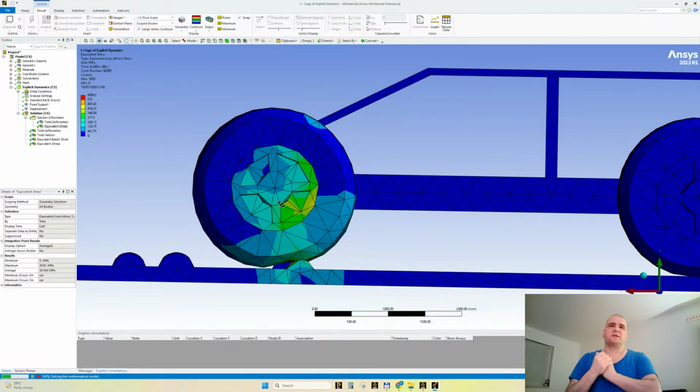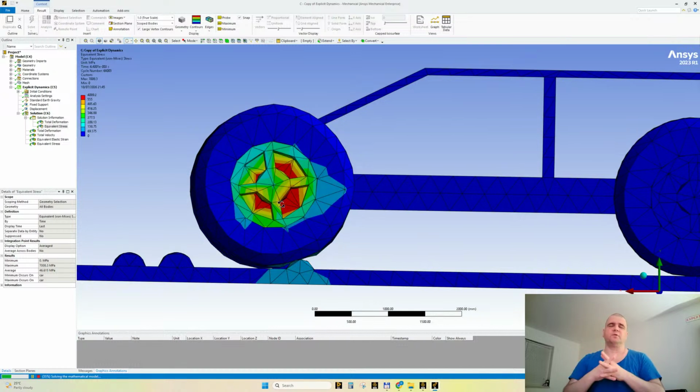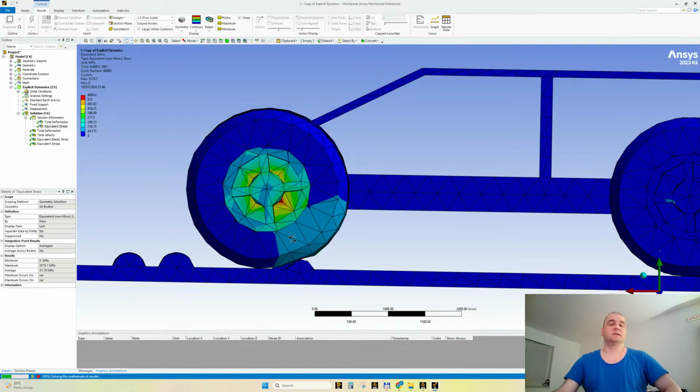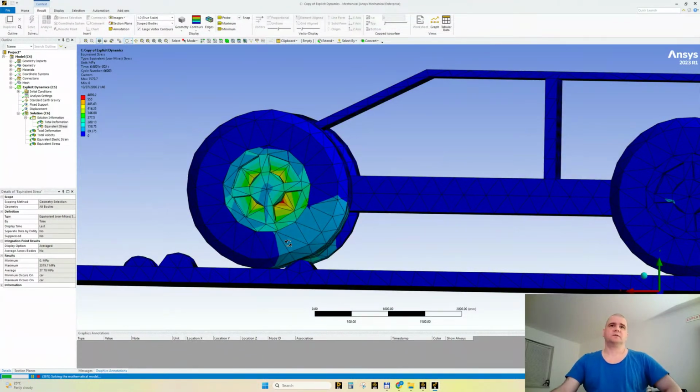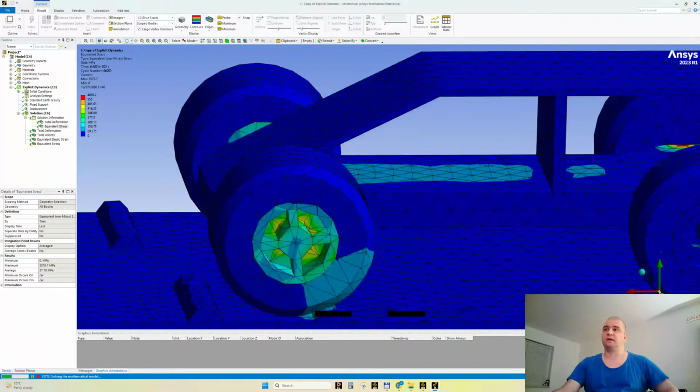As I have seen so many beginners, they make such an extraordinary looking mesh, and the FEA does not work at all. If we refine the mesh without having a working scenario, the usage is 0 for that fine mesh, absolutely 0. When we have a working concept, as it is here, then we can easily refine the mesh with the expected extension of the solving time. Yes, expect the solving time to increase.